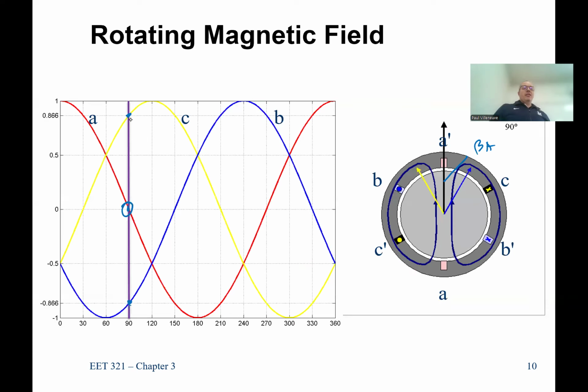If you were to do a sine wave, so this is a phase shifted sine wave. Well, so this is a cosine wave, right? If you phase shift a cosine wave by 120 degrees, plus or minus, you'd end up with plus or minus square root of 3/2 if this omega t was equal to 90 degrees. So it's basically the cosine of plus or minus 30 degrees.